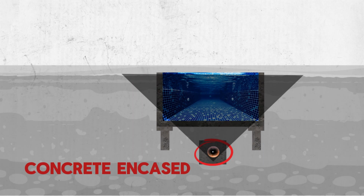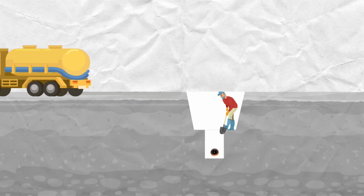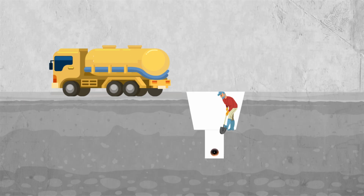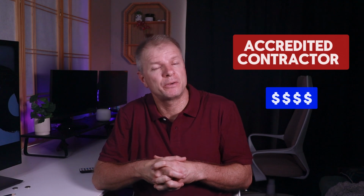Now the third option is when building over the top of a pipe. In order to gain this approval, the pipe would need to be encased in concrete so it becomes stronger and maintenance free in the future. This option would attract similar consultant fees as the prior option, plus costs for excavating around the pipe using non-destructive digging techniques, which can be slow and more expensive, than concrete encasing, backfill compaction and so on. Furthermore, this work needs to be carried out by an accredited contractor because we are working directly with the Water Authority's asset, and they will generally charge a premium as they are in high demand.